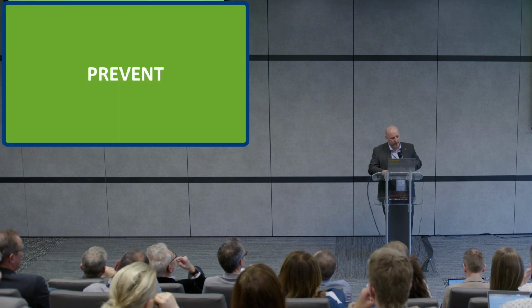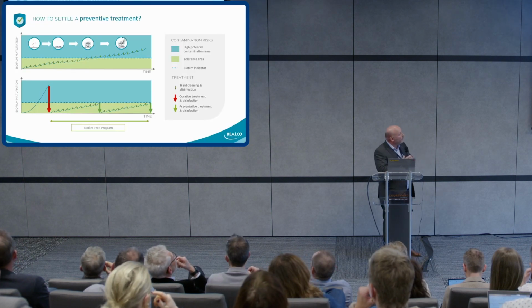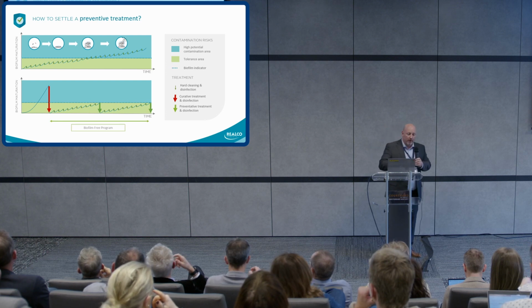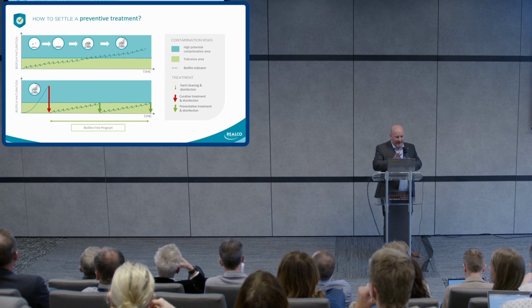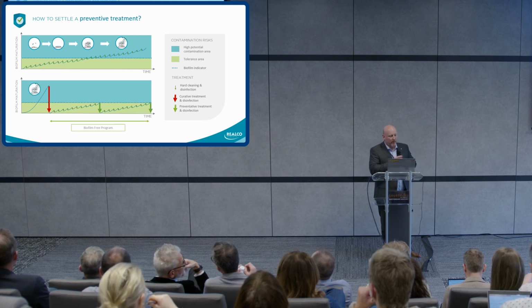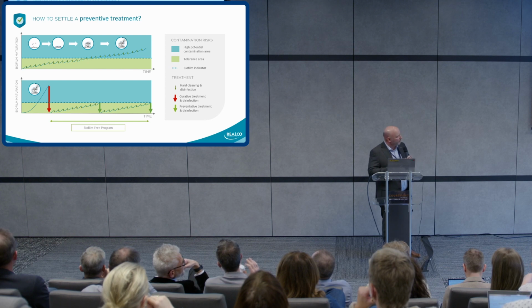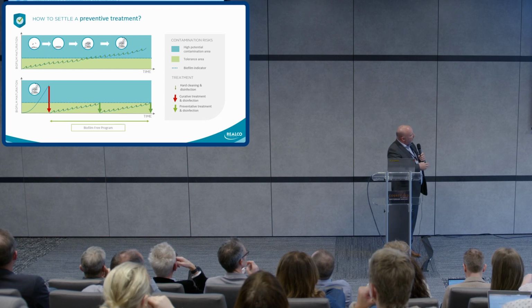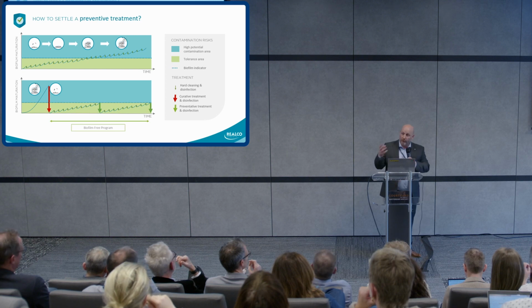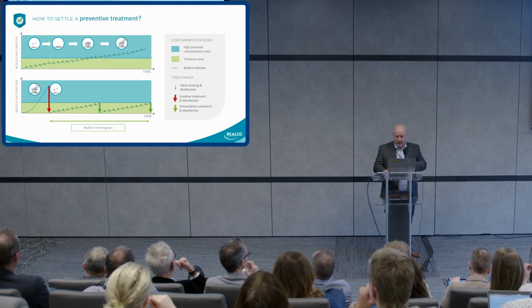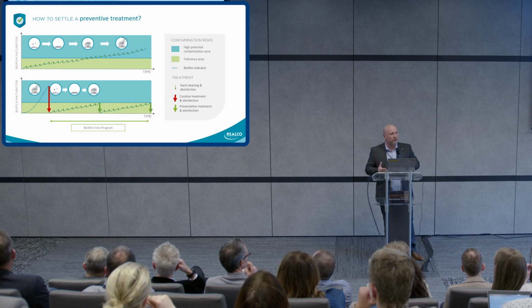On the top you see what happens with the 4 stages of the biofilm growth cycle, and when you are at the end, you see the contamination in your routine test. The idea is we start with a curative treatment, this is the red line. We go to a zero-level biofilm contamination. Unfortunately, it's not possible to avoid those germs entering your process, so we will try to follow and monitor this biofilm regrowth.